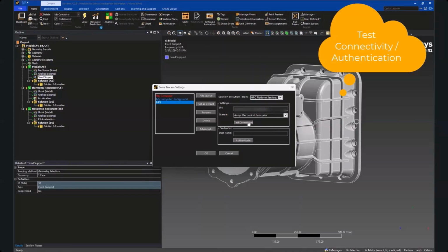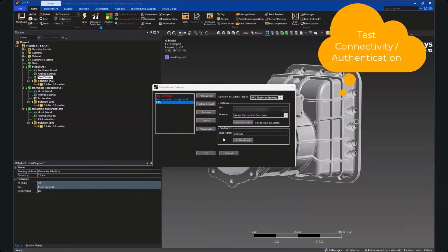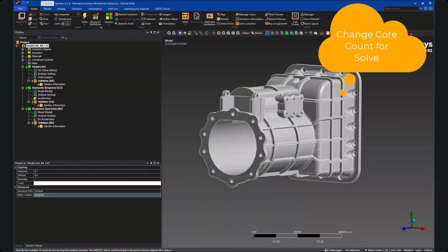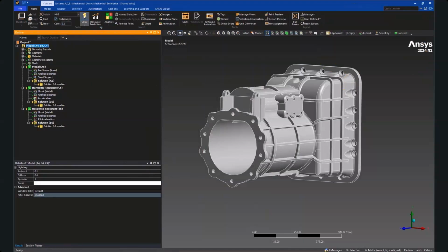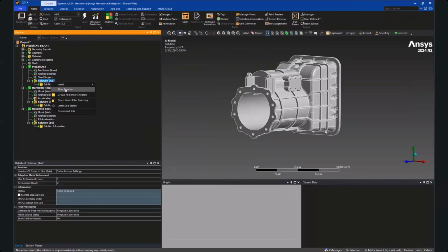We've validated both mechanisms. So this could be your local desktop, and you're connecting to HPS up inside Ansys Access for hybrid. So we're just going to test the connection. We validate the user, hit OK. Then we're going to change the cores. So okay, 32 in this example, we pick the HPS, and then we hit solve. So now the job is going from potentially your local machine up into HPS.